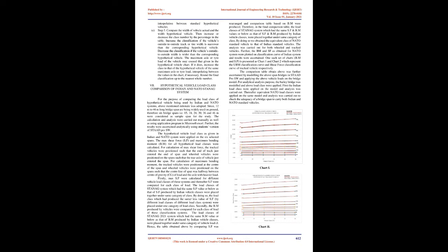C. Load on each wheel, empty and loaded. D. Tire size and pressure per axle. E. Number of tires per axle. F. Spacing between the axles. G. Width, outside to outside, of the tires or tracks and width, inside to inside, of the tires or tracks. H. Length of the track that is in contact with the ground.